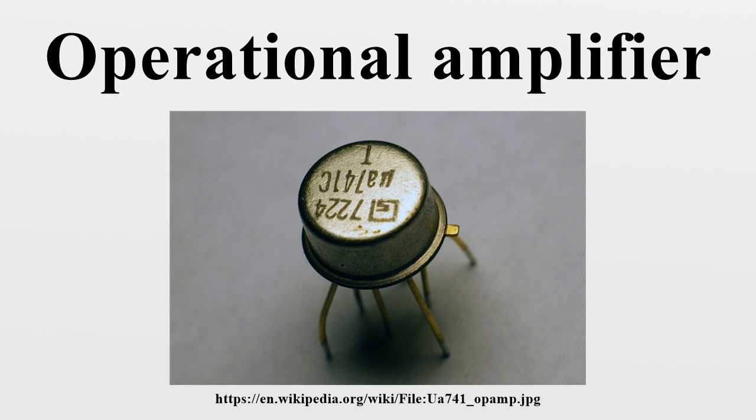Operational amplifiers had their origins in analog computers, where they were used to do mathematical operations in many linear, nonlinear and frequency-dependent circuits. The popularity of the op-amp as a building block in analog circuits is due to its versatility. Due to negative feedback, the characteristics of an op-amp circuit, its gain, input and output impedance, bandwidth etc., are determined by external components and have little dependence on temperature coefficients or manufacturing variations in the op-amp itself.